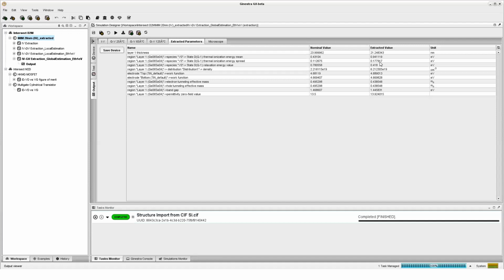So in this way, we have been able to characterize the defects of the material that contribute to the transport, so the ones that enter in the trapping and detrapping processes of electrons, of carriers, and we can use this data to perform additional simulation. For example, we can use these parameters in other devices that include the same material. But up to now, we do not have any knowledge of the chemical and structural characteristics of these defects, and it would be really useful to be able to distinguish among all the possibilities.